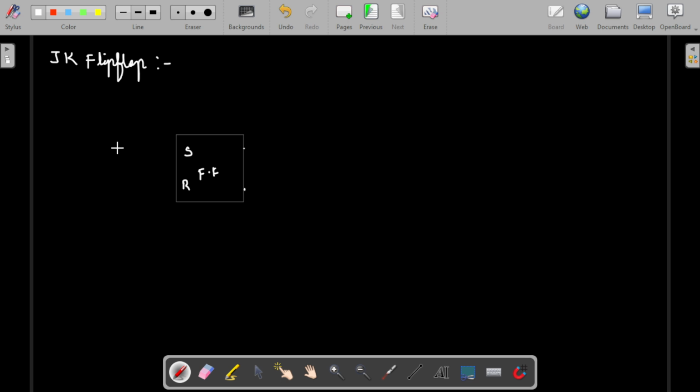The only extra thing we are adding is that here the clock is also the same. Everything here is the same. Here we will be adding an AND gate. To the AND gate, one input is K, one is J, and the next input is connected to the toggled, inverse version of the output. So let me complete this one.